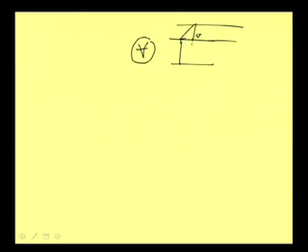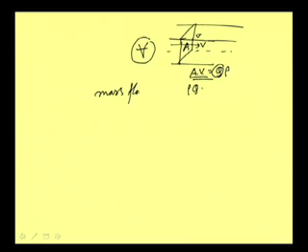Suppose this cross-sectional area is A, and it is flowing with a velocity V. Then A into V is equal to Q, area into velocity is equal to Q. And then this Q multiplied by rho, rho Q, gives us basically the mass flowing per unit time